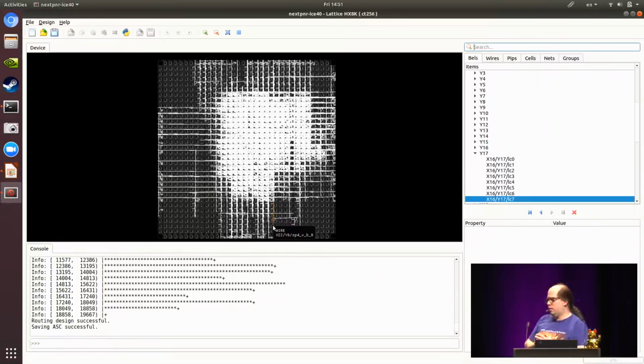Since the tool generates this sort of a blob of logic in the middle, won't the FPGA overheat in the middle while being basically cold on the outside? So wouldn't it generate a huge temperature gradient? No. There are reasons why I would like to have things fanned out a little bit more over a wider area, specifically to help with routability.